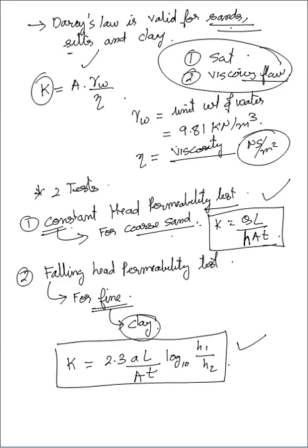You should remember, for sand we apply the constant head permeability test, and for clay or fine soil we apply the falling head permeability test. Okay, thank you very much.